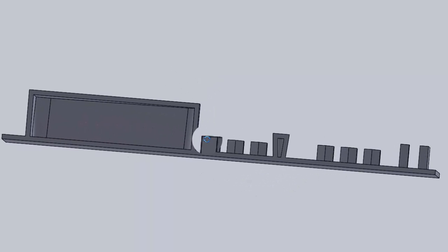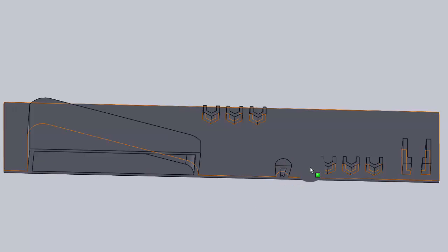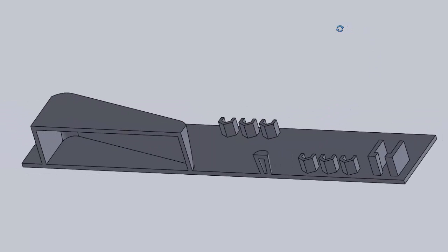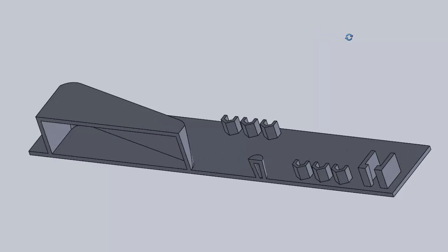That's why, for example, I have spots for the bits right here, but I couldn't put the other spots for extra bits up here, which made more sense in terms of use. I had to put them here. If I put them here, there's no way to get that cavity out coming this direction unless you increase the cost of the mold dramatically. The way I have it designed, all you need are two halves.